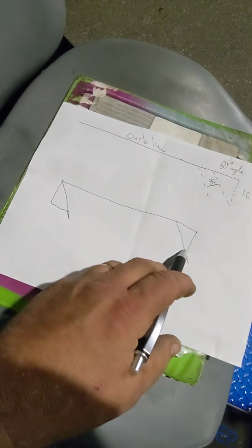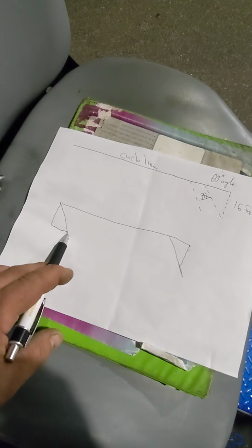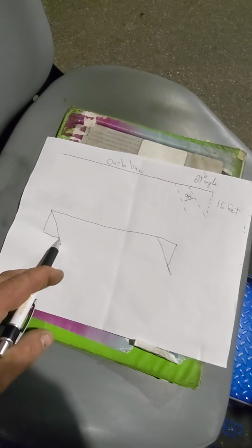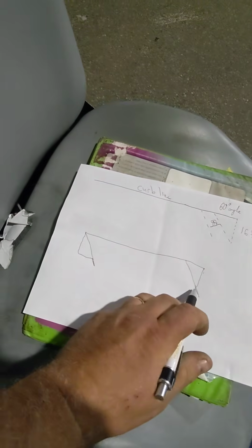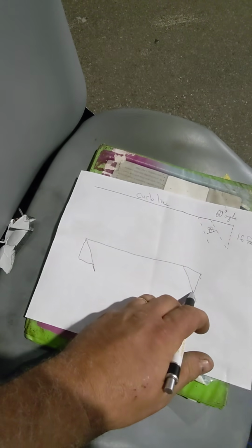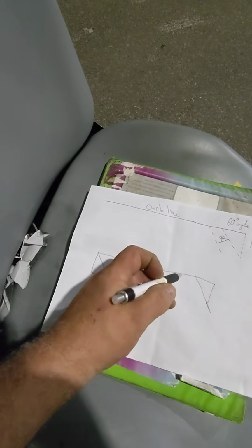Then what we'll do is we already have our 16-foot or wherever mark they established chalk line installed. Drive very straight and measure from this mark to this mark in your regular layout menu, not in the angle layout. Then you divide it by the number of stalls that you need, and then you're done. Then you come back here, pre-mark. This is where it gets tough. You have to get the same pre-mark along the curb line, so your first stall will line up.